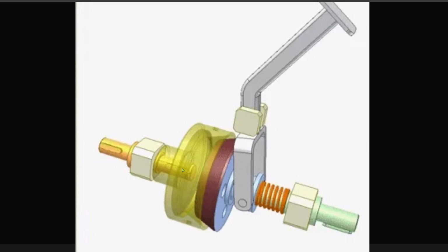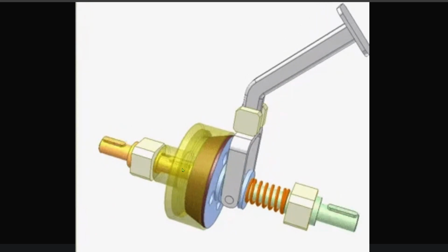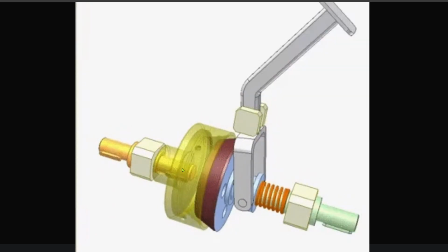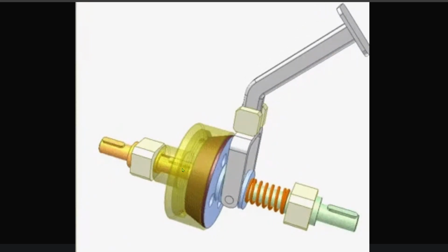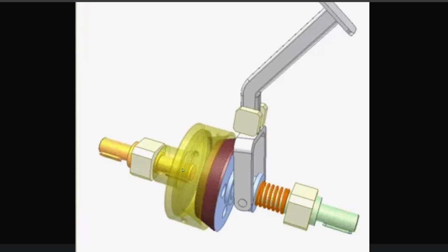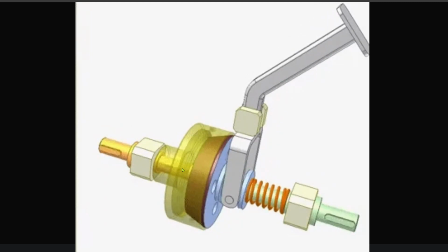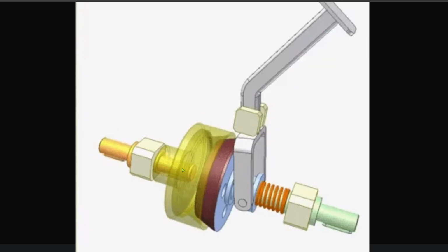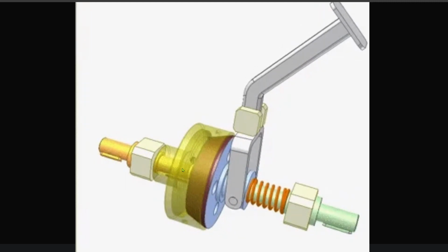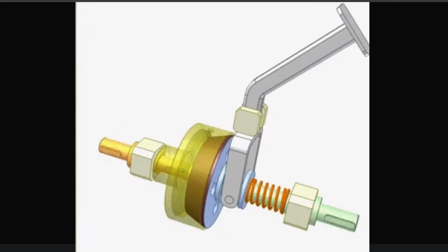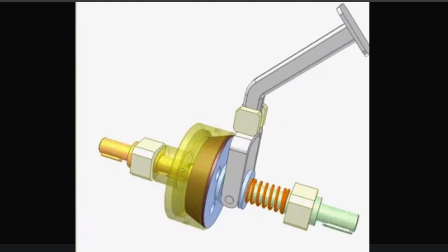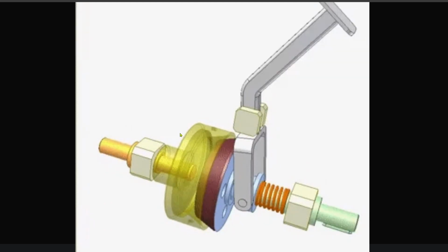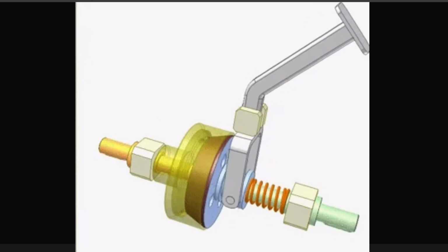So for example, when you come to a stoplight in a manual car, you need to push the clutch pedal in to disengage the engine from the wheels, because if you're stopped, the wheels are now stopped. And so what would happen is if you didn't put your clutch pedal in to release the clutch plates, you would cause the engine to stall. The brakes on the tires and the friction from the ground would actually stop the engine. And so we can't have that. We need the engine turning in order to make compression and keep the engine going.